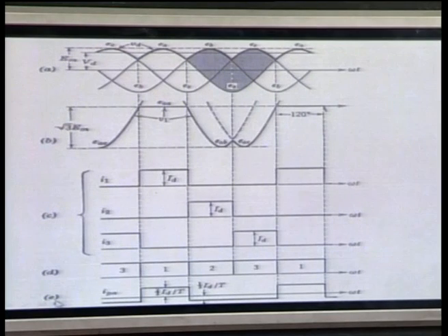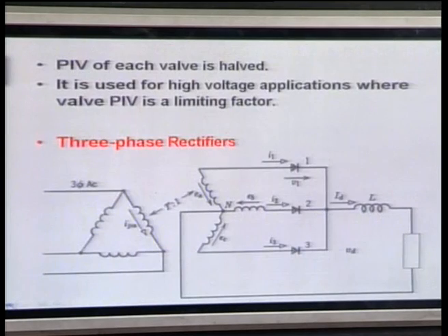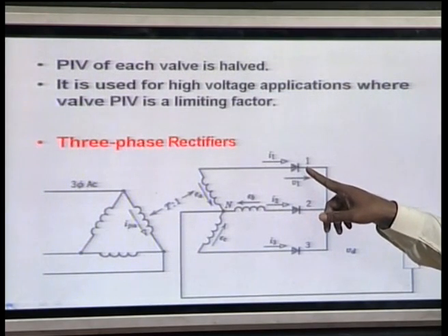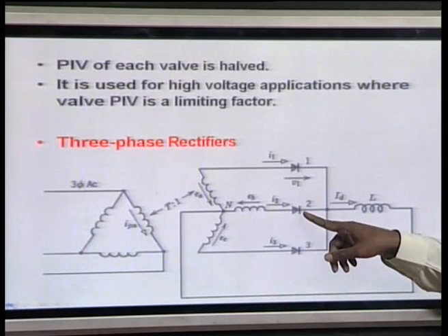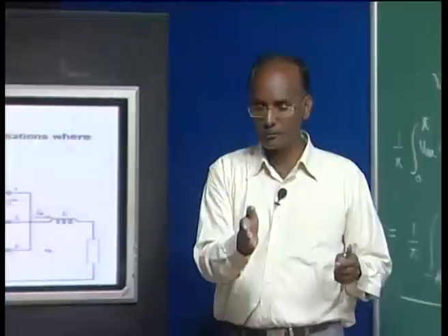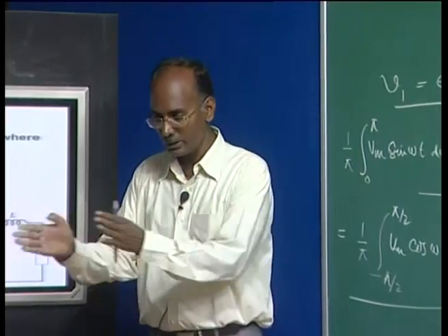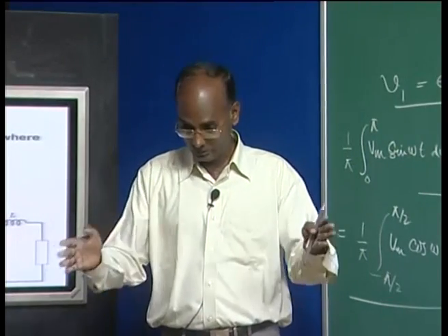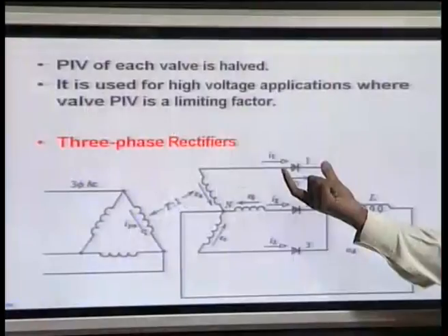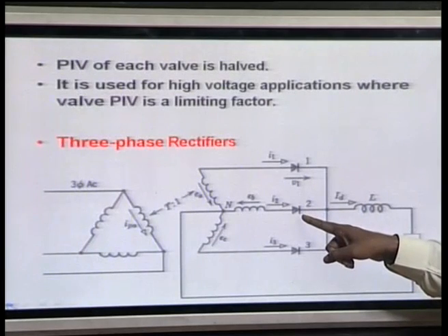the voltage which appears in this circuit, again you can see how much voltage we are going to get. Now, once valve 1 was conducting, its voltage was 0. Now, the next turn of the next valve, we are assuming that we are giving the pulses at regular interval. It is not that it is just off. We are assuming this is a continuous pulsation. There are 3 valves, so in 360 degrees each one conducts for 120 degrees. After that the next valve's turn comes and it is fired.